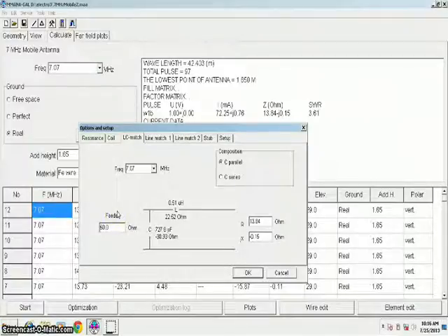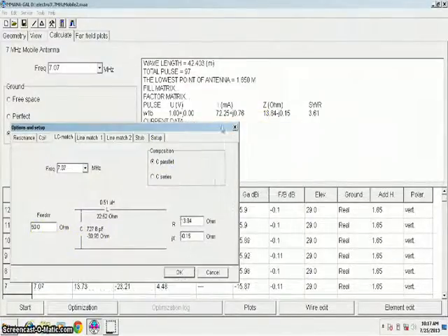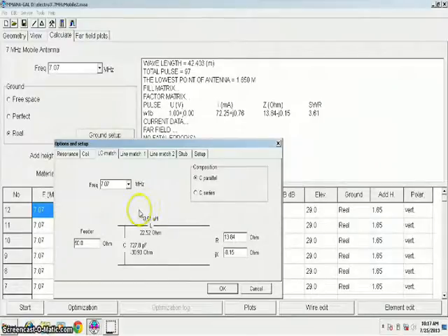The transmission line used at the mobile antenna is RG58 or RG8, which the characteristic impedance is 50 ohm here, and the output should be 13.84 minus 0.15, and this is the matching system.